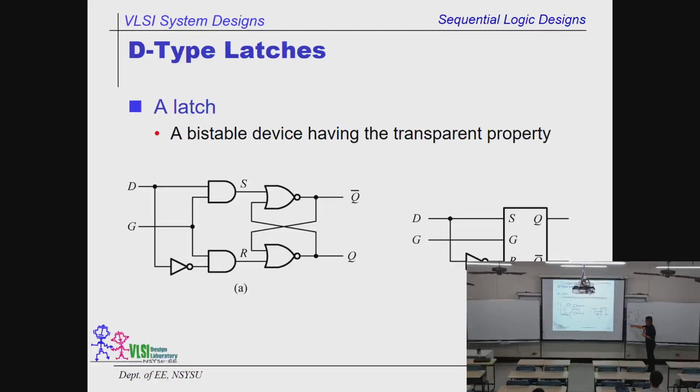Because it's inverted, because you use the inverter here, no way you are going to have these two conditions. So you simply eliminate these two because of the inverter. So it's gone. Now when D is high, this one will be low, or the other way around. When this is 0, that will be high. So this is 1, 0, it will be this case. If it's 0, 1, that will be this case. So it's either set or reset.